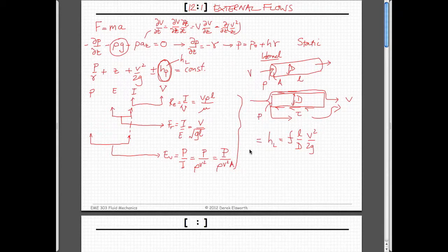And this also is equal to what? The units of this are equal to the pressure applied on this surface, the difference in pressure between the upstream location and the downstream location. It would be the same here, right? There's some pressure here due to stagnation, and you'd have a lower pressure at the back side, so physically, a force would have to be applied to this to be able to keep it in place. And so this is a pressure divided by a unit weight of fluid.